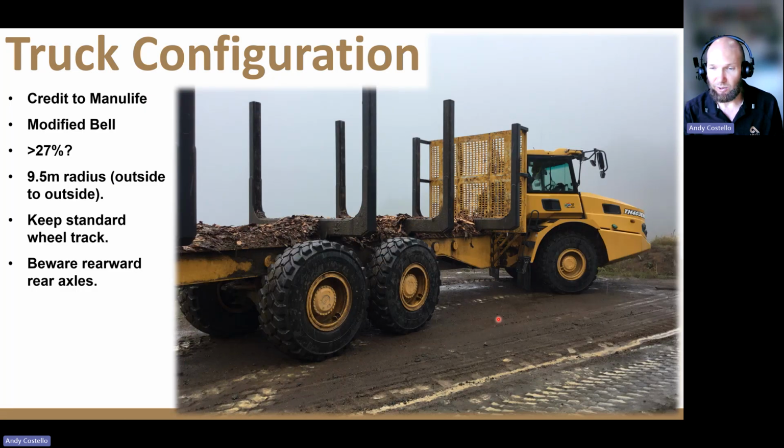Also, these ones here, you still need to understand how steep they can go and what sort of room they need and what corners they can go around so you can build an appropriate road. I won't get into that in detail, except just to say that with these and the 6x8s, as well as designing the road, you also want to consider a bit more how it's going to be built. Consider how you're going to spread metal on a 20% grade.